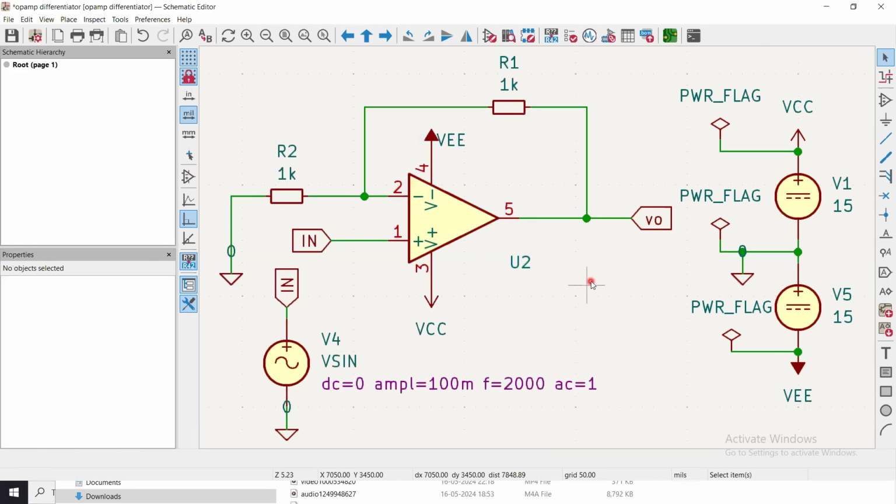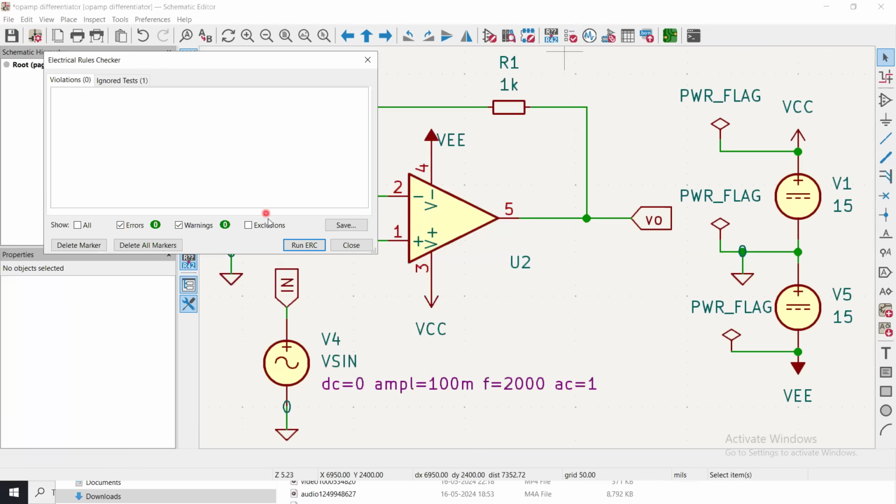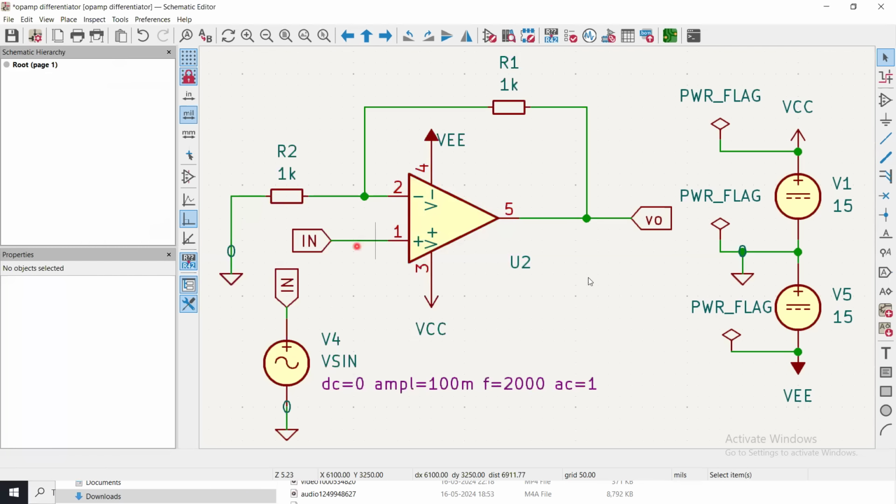So we are done with this. Everything is correct. I have explained to you how I use the components, call the components and the devices from the model library, how I call the sources, how I made the interconnection. Specifically, I explained how to use the model parameters and so on. So it's going very well so far. Now we have run the ERC also, and there are no errors right over here. Good. Since there are no errors, we are all set to run the simulation.